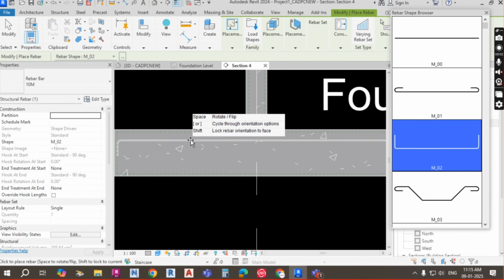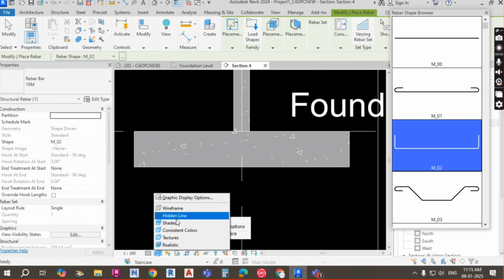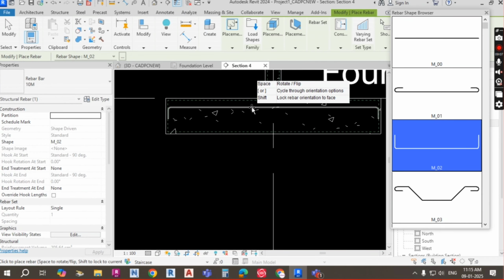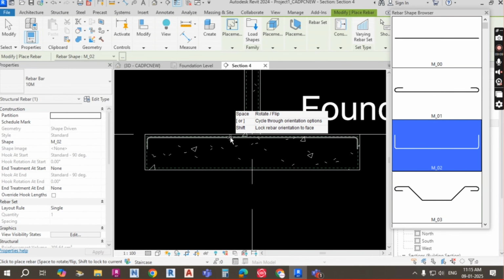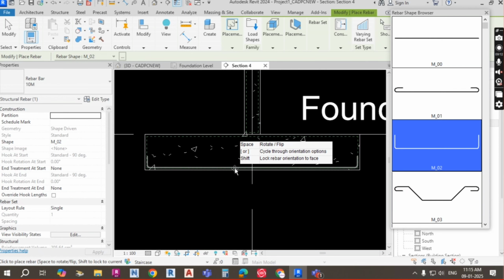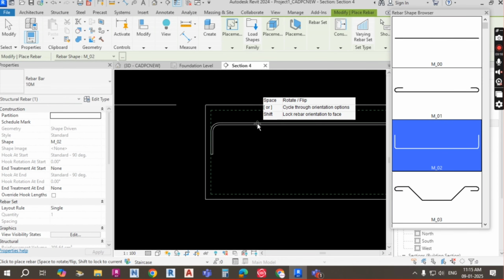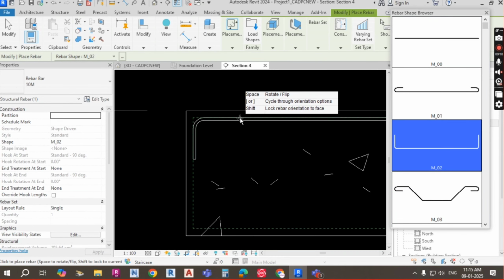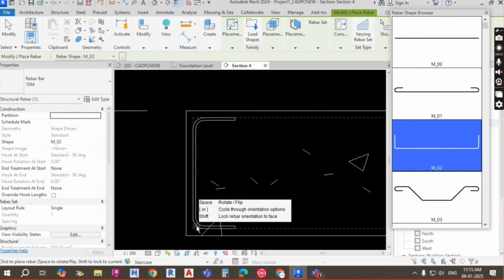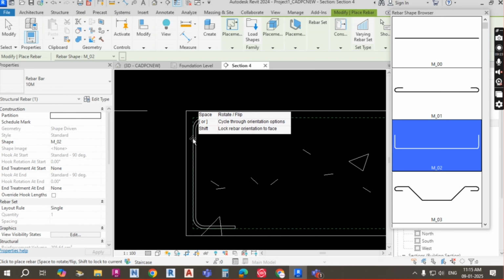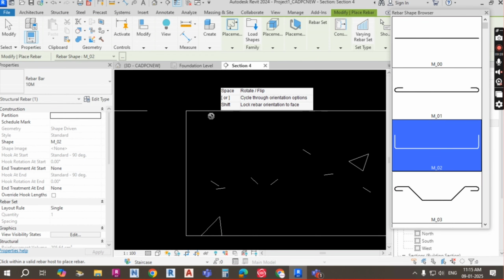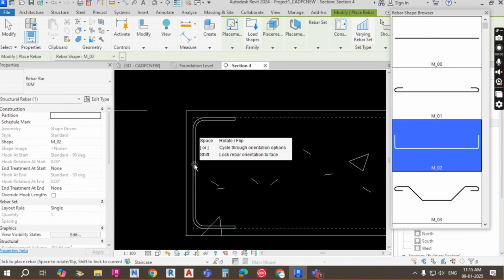Now I am going to place the top rebar. If you go here in the hidden view, you will be able to understand. Now you can see that when you are clicking here, automatically this is the top, and if you come below, this is the bottom. You can see here there is a dotted line. That dotted line is nothing but the clear cover area, because your concrete comes to this outer boundary, and this line gives the gap from the outer line of your RCC model. There will be a gap, and between that gap you have to touch and place the reinforcement.